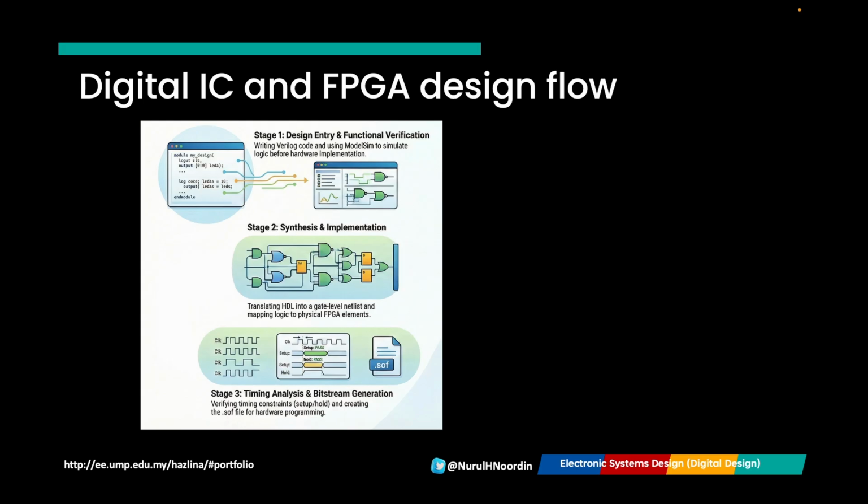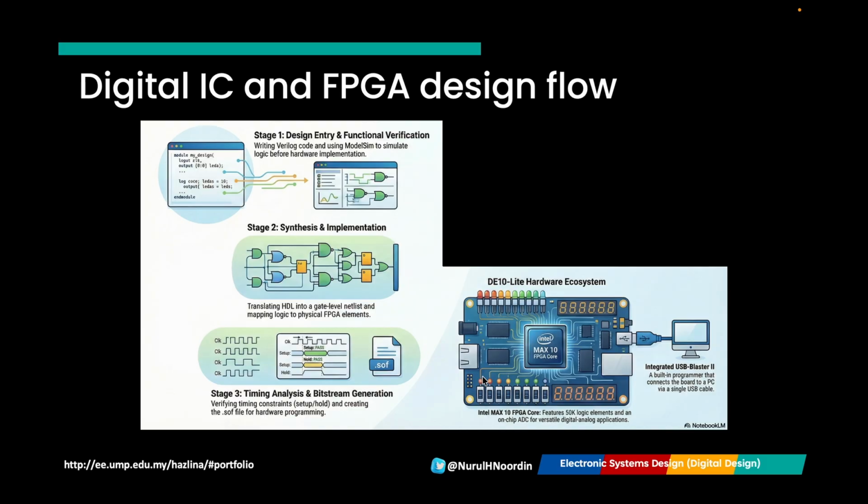Once the design successfully passes synthesis and timing analysis, the compiler generates a bitstream file for Intel FPGAs. This file contains the completed binary configuration data that instructs the FPGA exactly how to configure its internal hardware connections and logic functions.